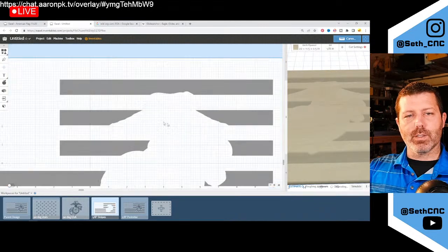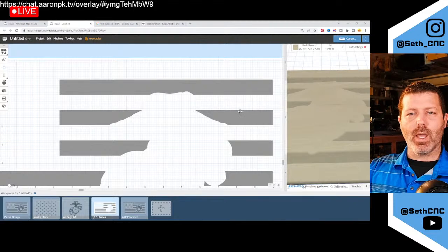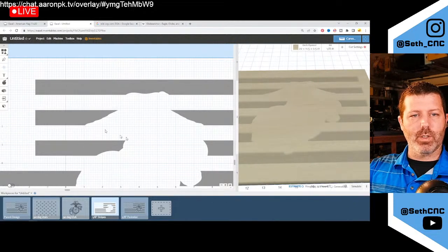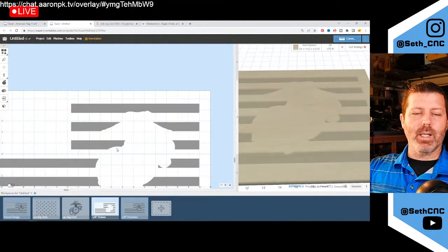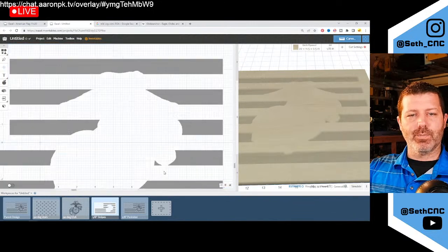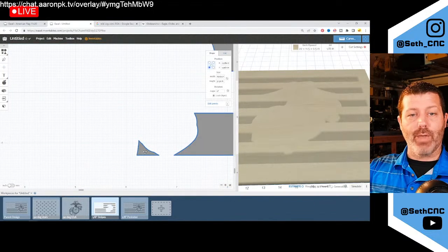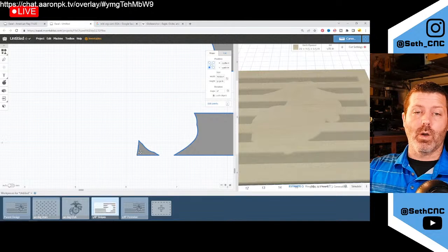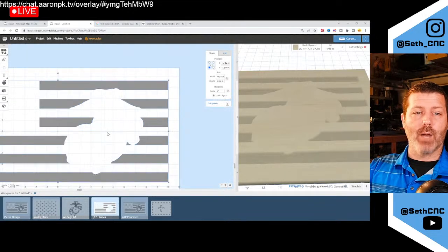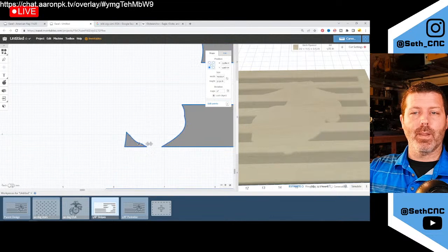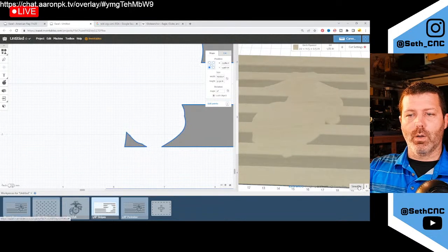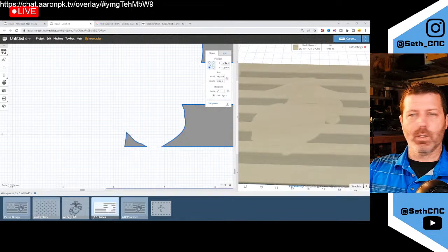Now, some of these areas of the stripes, the end mill that I'm using can't actually get in there, and that's okay. It's just going to kind of round out some of these super sharp corners. With a logo like this, you're never going to notice that. Now, something like this little bit here, that I think looks funny. So I'm going to delete that out. And you've got a couple options on how you delete that away. But here, we can run this simulation, I think.